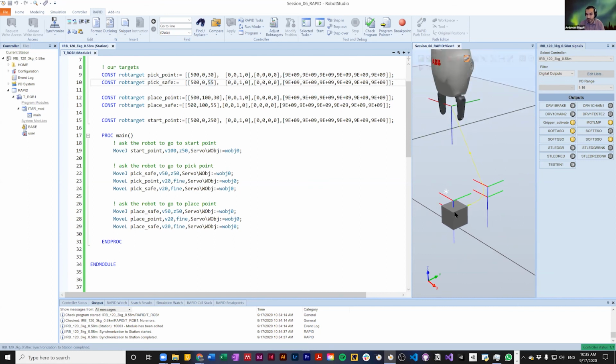I needed to increase this number, because I think this 25 millimeter is shorter than these fingers. And when the robot arrives at this target, the fingers are already touching the tool. I want to raise this number into something like maybe 65, or maybe 75, or maybe 70, best case.